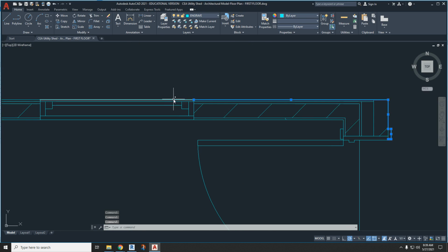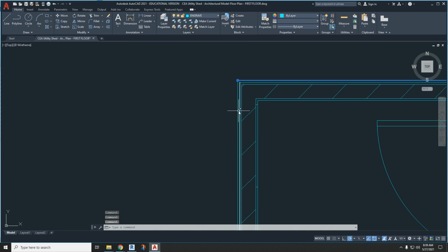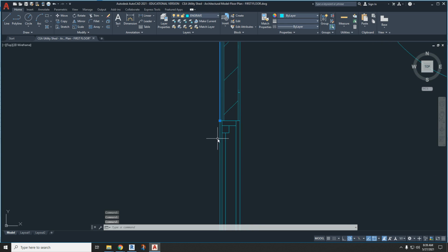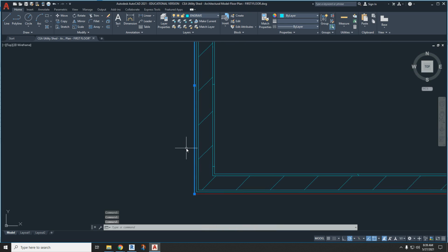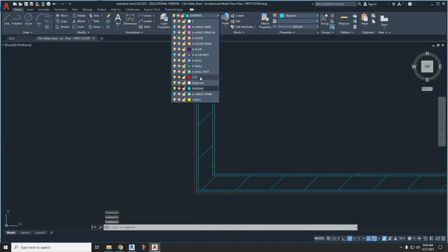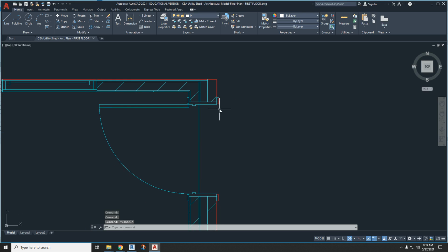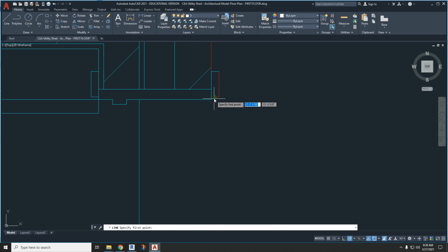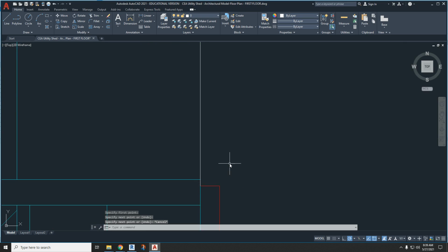Just keep going around. And this. All right, and switch all those to cut. And then you can actually draw a line here. So here's the line tool. You can click on it here. You can type in the letter L and enter, because AutoCAD was originally a DOS-based system. It still has a lot of the commands available for you.